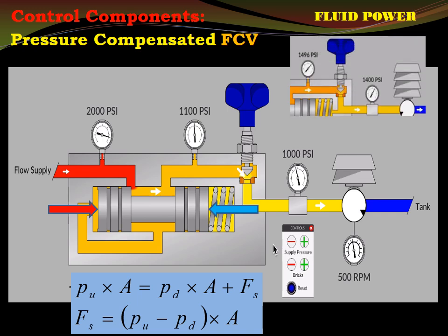Say, try to recall this part only. Pressure is 14,000 psi here. As this has been changed, that means this has been changed. This is fairly constant. So definitely the compensator spool will now be moving towards left.